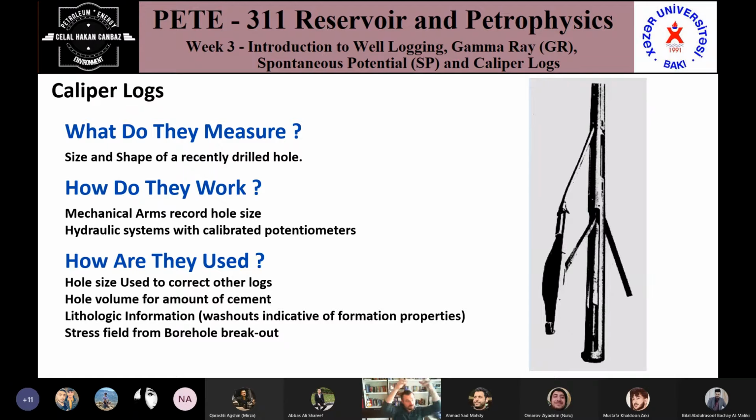So it records this change, and according to that, it says that the diameter at 1,220 feet, for example, is 35 centimeters or 55 centimeters. So with the elevation, it gives you a direct measurement of your borehole size.